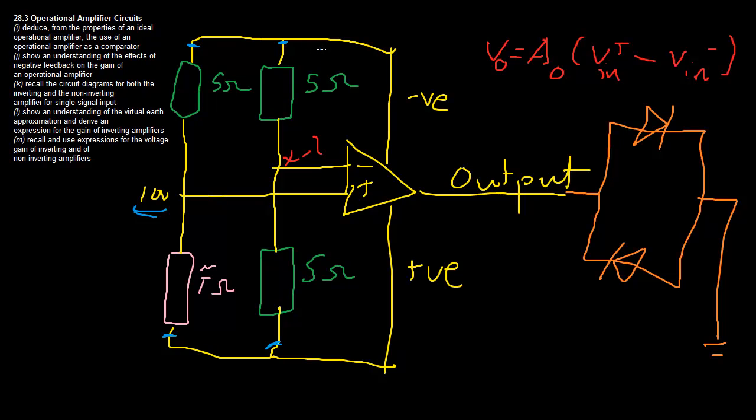And the reason for that is when the electrons split up here and later rejoin down here, if we just think about this kind of big square in isolation, the voltage of these electrons is the same at this point, and when they rejoin, the voltage of the electrons has to be the same as well, because when they become one unified stream again, all the electrons in that stream must have the same property, because electrons are fundamental particles and therefore are all exactly identical. So 10 volts is expended between these two resistors here, and 10 volts is expended between these two resistors here.